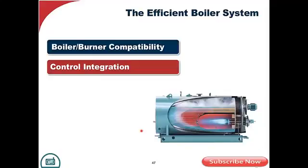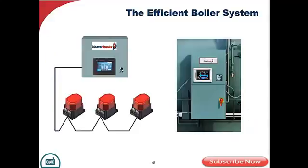And of course, what also is very important is how do we control these boilers from a burner management standpoint and a combustion control standpoint. Let's get rid of the single point positioning. Let's go with parallel positioning. So I get rid of the hysteresis and the stretch and the slip in those single point positioning linkage arms and rods.